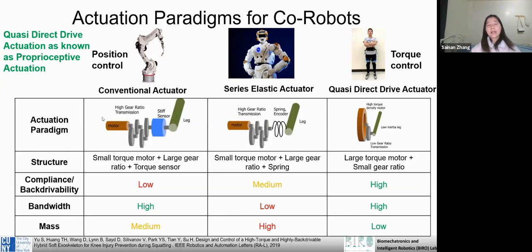That means, for example, if the inertia is 1 and the gear ratio n equals 100, when we rotate the leg, the work we need to do goes from 1 to 10000. So it will amplify, and it creates a large resistance.